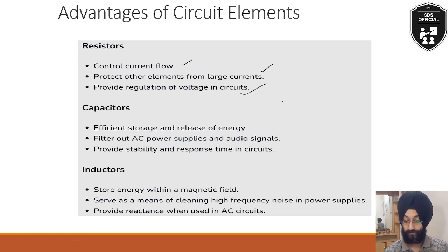They can also filter out AC power supplies and audio signals because they allow AC, alternating current, to pass through themselves and do not allow DC to pass through. So if a variable signal and a DC signal are present in a combined, complex signal, they can easily filter out the AC signal. They also provide stability and response time in the circuits.